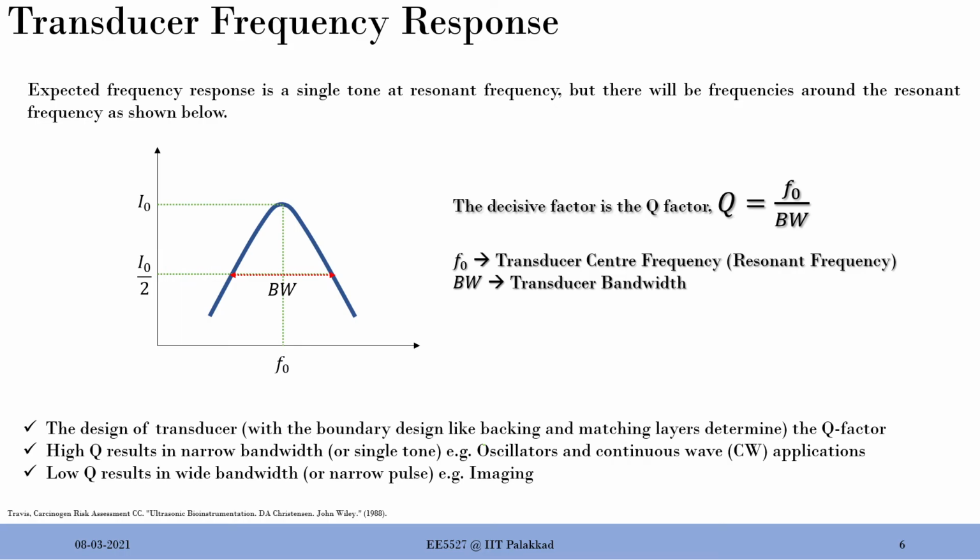In imaging, we want to send a narrow pulse. We want to restrict the signal in time. You want to damp the waveform so that it won't extend infinitely long, restricting it to a narrow pulse, and the moment you restrict in time, you expand in frequency. Those who have not understood the Fourier transform will have trouble understanding that.